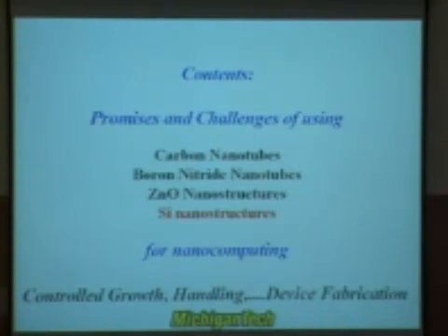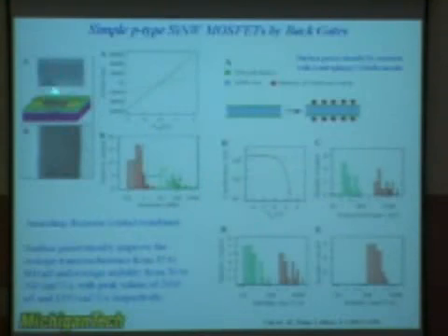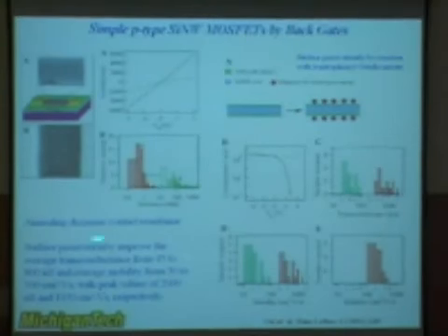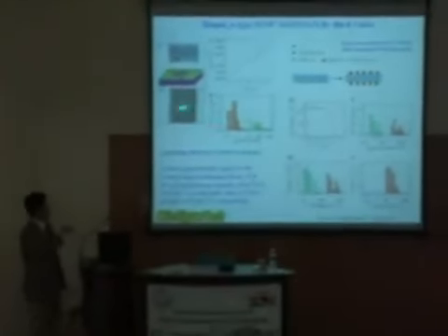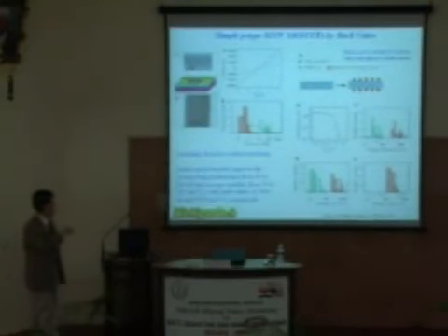So let's revisit the possibility of silicon nanostructures. We actually already have so-called silicon nanowires, right? It's just a one-dimensional silicon structure. And it can be grown at a diameter of 10, 15 nanometers. And actually, the device is already shown here, one piece of the wire across source and drain electrodes. And what was discovered by Harvard University in 2003 is that annealing will decrease the contact resistance between the wire and the electrodes. However, they found that they need to do surface passivation.